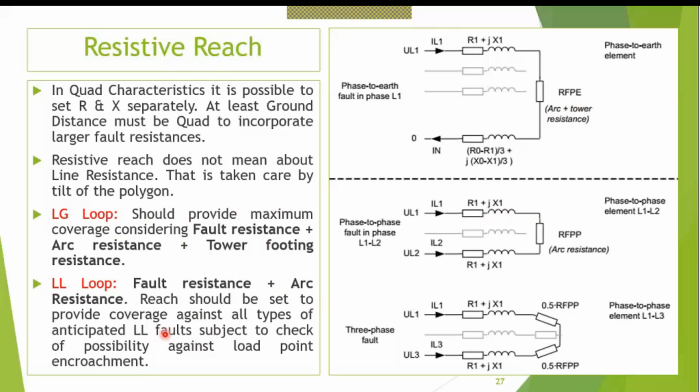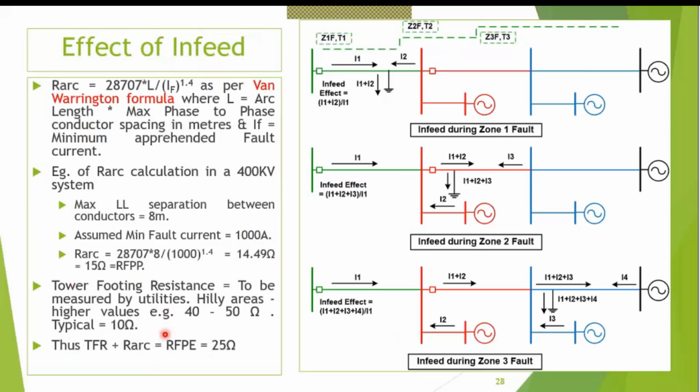So we'll have to set the line-to-line resistive reach a little bit carefully because load encroachment can happen. We have separate slides on how to calculate the load encroachment and all that. Effect of infeed. Now, this is another important area.